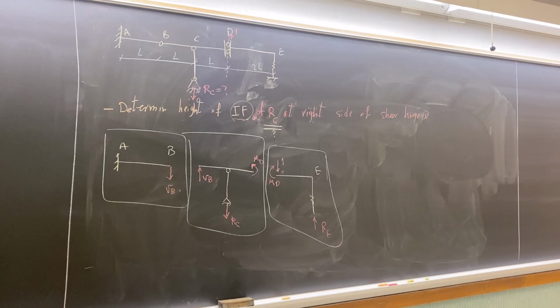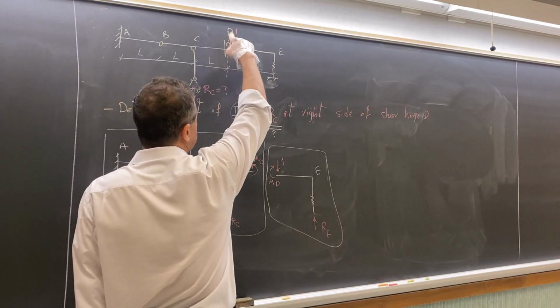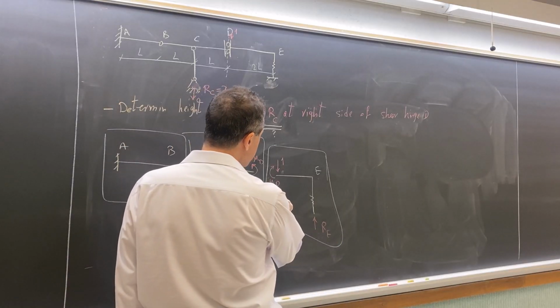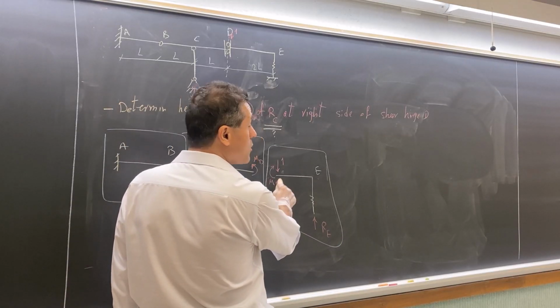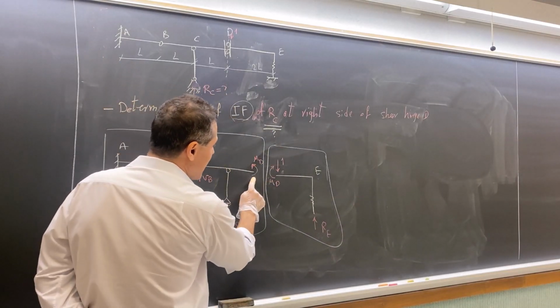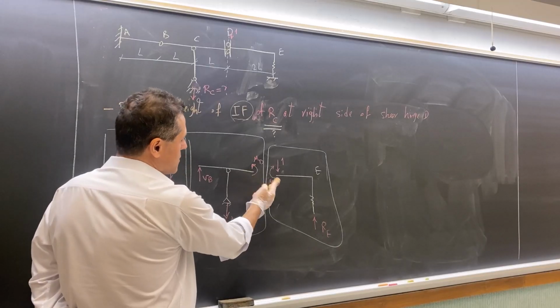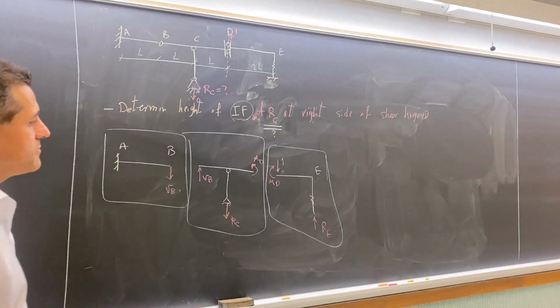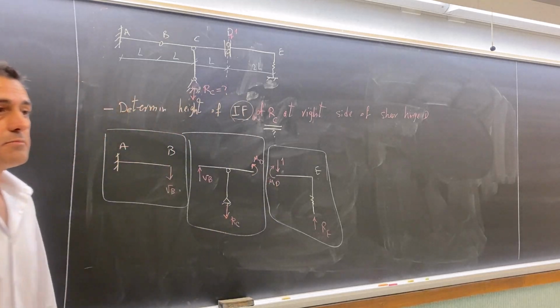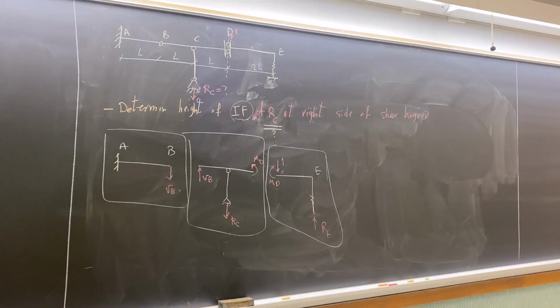We are looking for RC. To answer the question from Clement, he said this shear hinge is free to move vertically, but do you think MD has a value here? So it carries the moment, right? That moment has a reaction at this side. So basically we have a moment here, we calculate this moment, and then we calculate RC, because we are targeting finding RC.